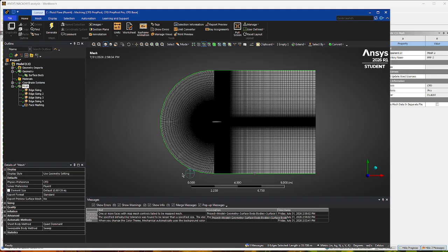And all of this counts as our inlet, just because it would be a reason to cry if we just switch the geometry every single time we have to change the angle. So instead of doing that, we're just gonna change the angle from where the air comes from. So 0 degree, the air is gonna come through here, and if not, it's gonna come through here. So in order to do that, we need to make all of this the inlet.